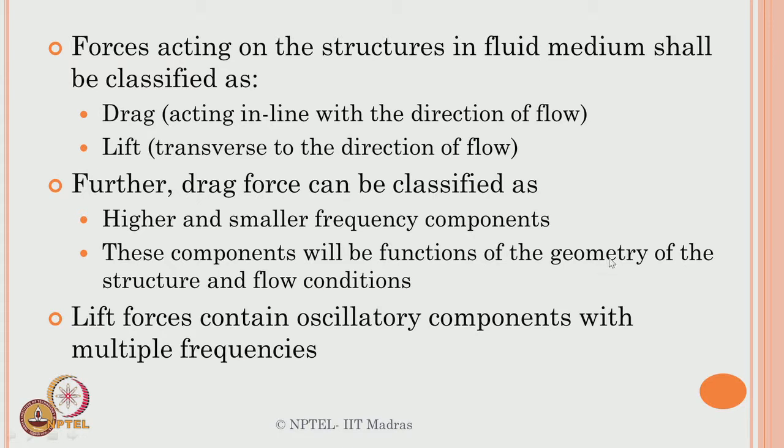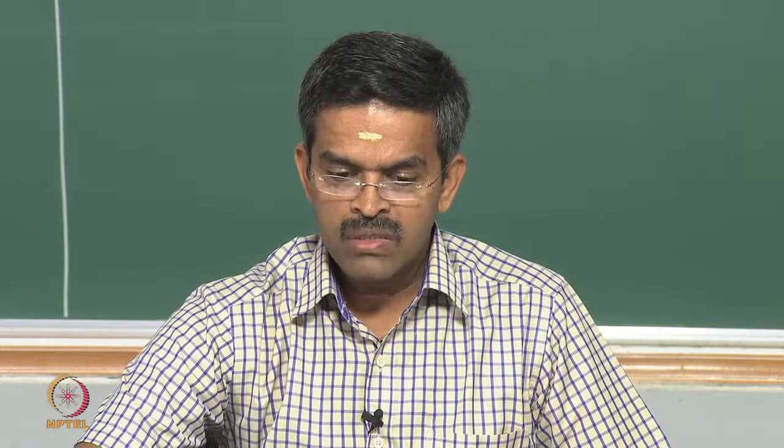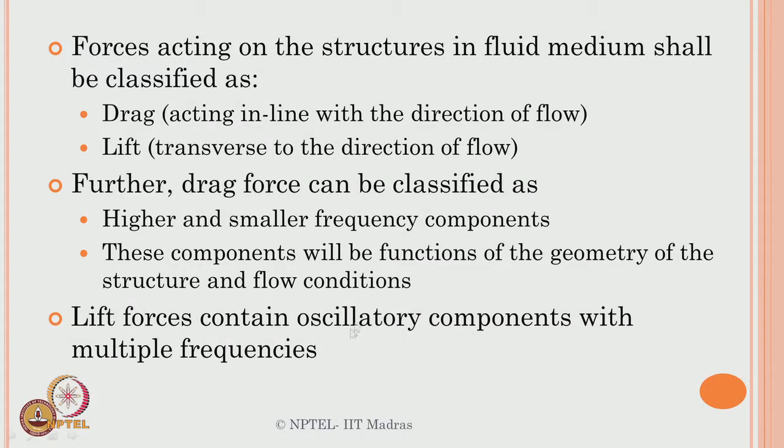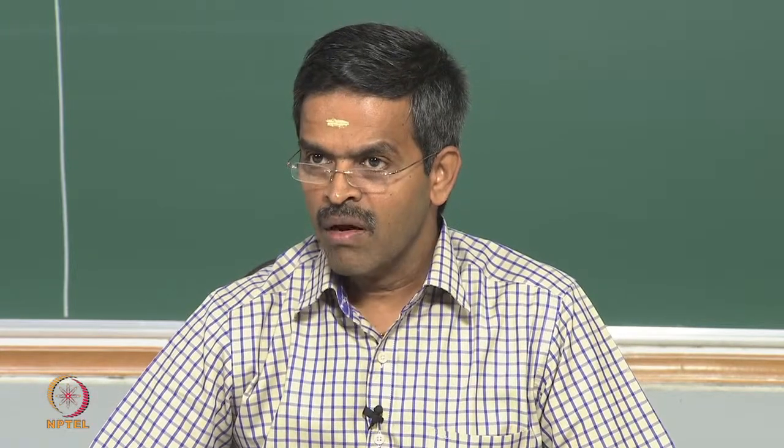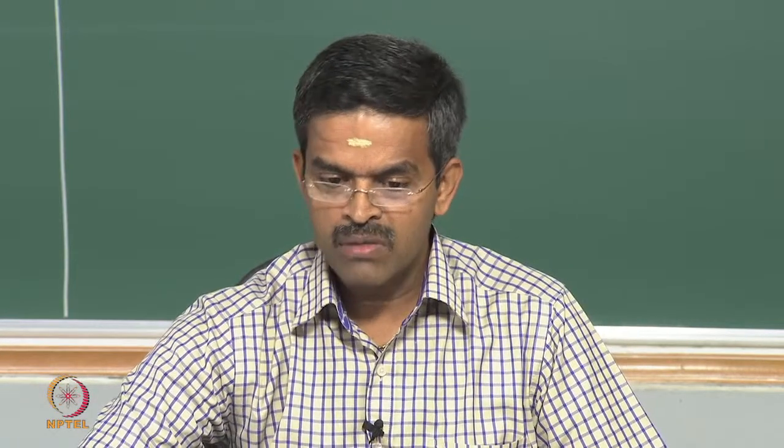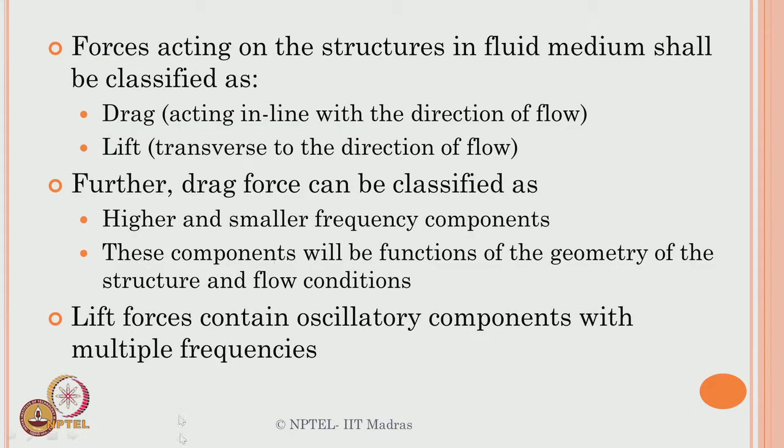Now, interestingly, in any classical structural design, forces are estimated on the members and the members are designed for the given forces, whereas here the geometry induces forces on the system itself because of its interaction with the medium. The lift forces, which are transverse to the direction of flow, contain oscillatory components with multiple frequencies, which are also important. Now, you have a member which is displaced in the direction of flow because of the drag effect, and which is also vibrating with multiple frequencies in the direction normal to the flow, which is transverse motion. So, now the member is interactive in both components.